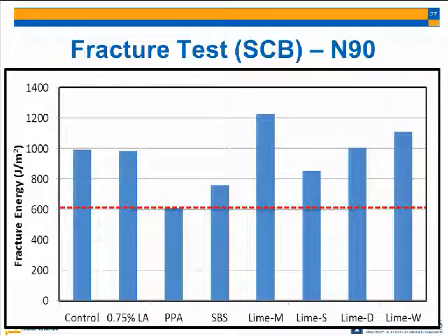For the first question, about the SPS: the SPS does improve the binder at high temperature, but that doesn't mean it can give you a better fracture energy at lower temperature. So it depends on what kind of polymer you are using and the impact at that specific temperature. So it's very, very